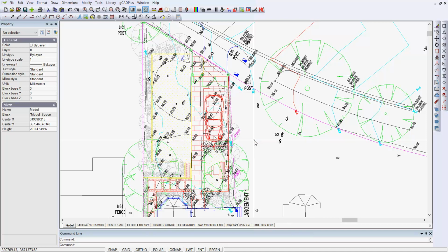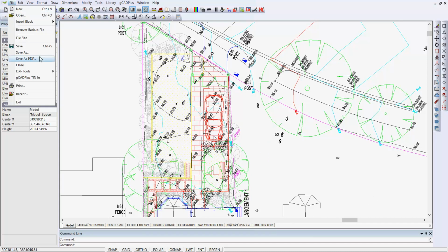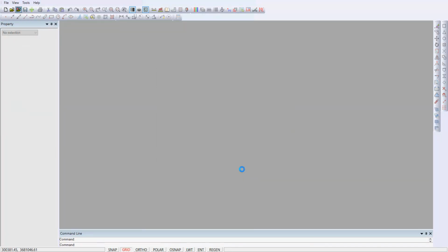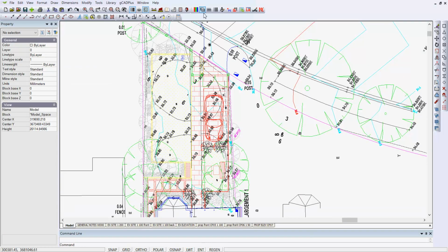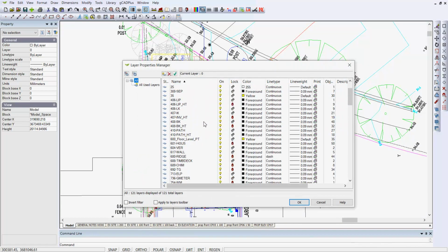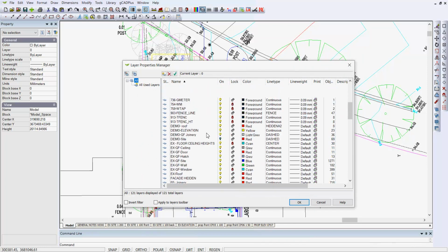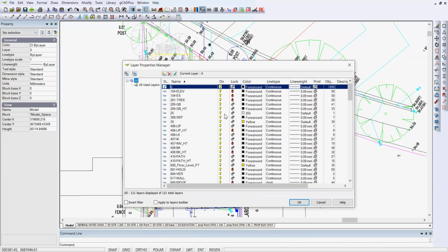So we can OK that, and we'll do a save and a close just as we did before, and then we'll open the Demo 2 and look at our layers. Now all used layers are there, and they all have something on them, so we've cleaned up, we've already made a substantial change to the drawing. Really worth looking closely at the information in this layers palette.